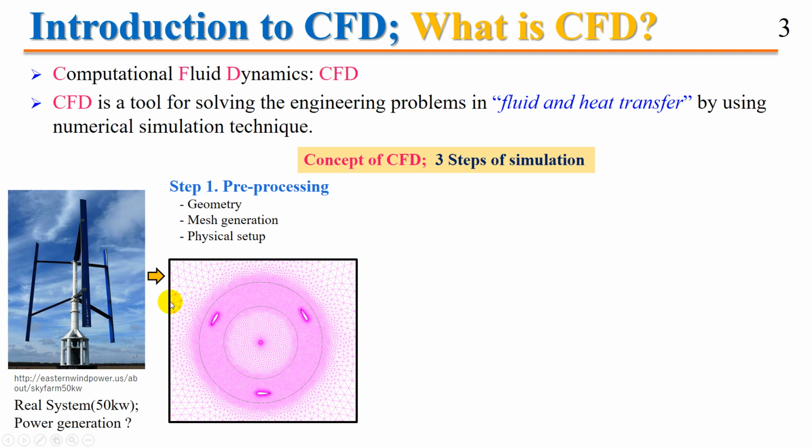You should set up the geometry. This is the geometry of the aerofoil, and this is the shaft. And you should prepare the fluid domain, including the inlet and the outlet, or the upper and lower sides of your domain. This step is really important.